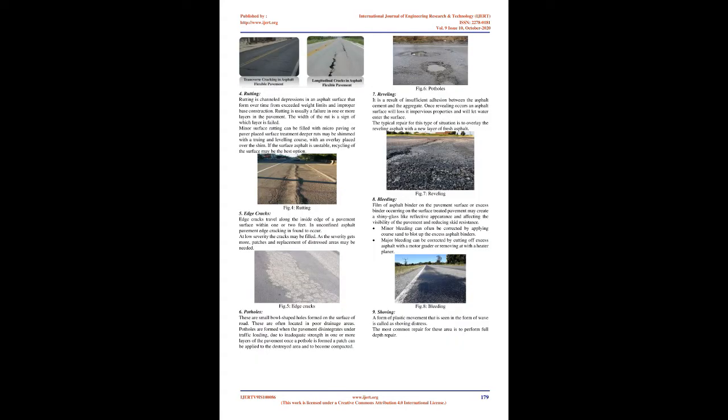Alligator cracks are also called map cracking. This is a fatigue failure caused in the asphalt concrete. Alligator cracking is commonly found at intersections where vehicles are stopped for a continuous amount of time.